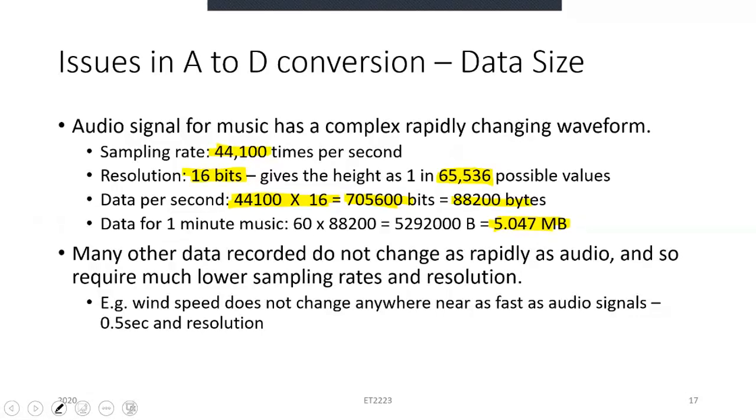But one of the things that we can do to reduce this is change the sampling rate. That is what we do when we are thinking about telephone signals, because the main intention there is to carry human voice. That doesn't normally need 44,000 as a sampling rate. So we may do something like 10,000, and that would be good enough for a voice.